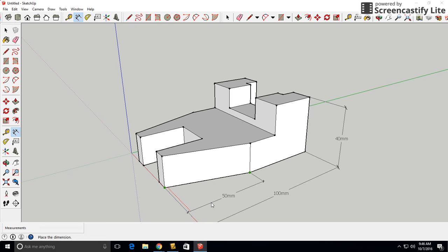Now, we work from the outside in, so the largest dimension is always on the outside. As we get nearer to the drawing, the dimensions decrease or add in the detail. Now, the leader line for this, I'm going to put approximately halfway between our initial dimension and the drawing, so I'm going to leave that one right there. So those are the first few dimensions.